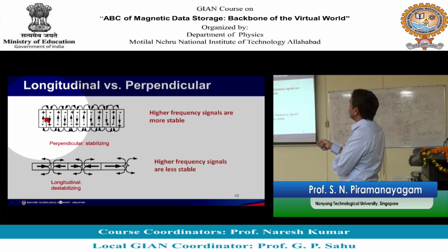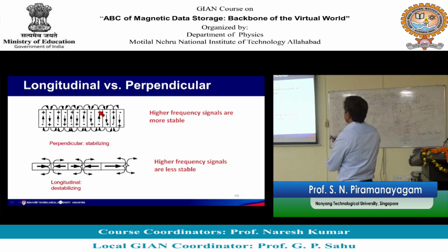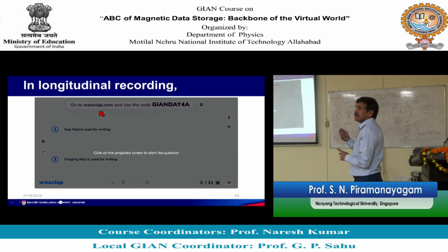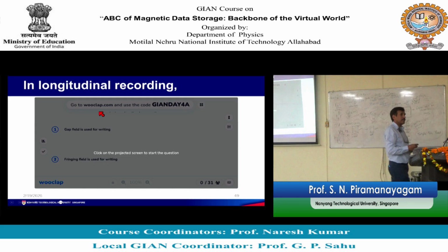Okay. On the other hand, if you pack perpendicular bits, so it is like north, south, something like that. This is very highly stable. So, because of all these reasons, the perpendicular recording technology is better than longitudinal recording, and in 2008 the perpendicular recording fully took over the longitudinal recording. Okay, so, let us do some questions.